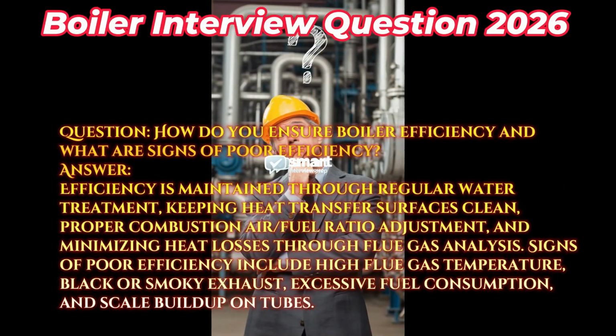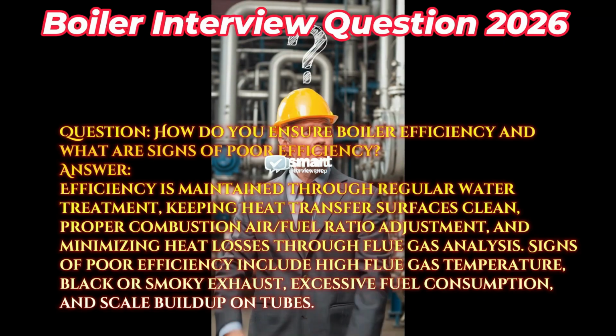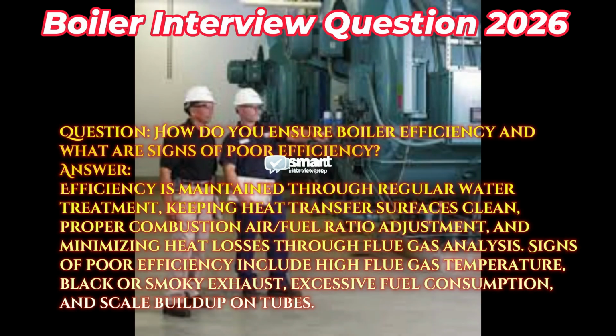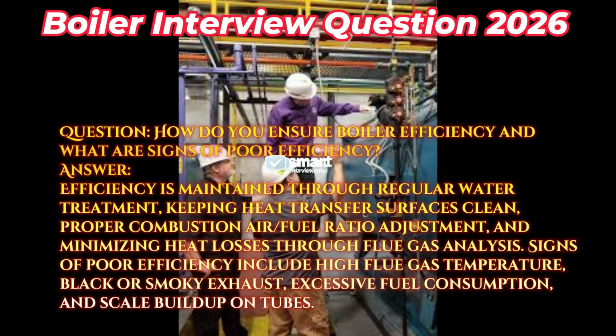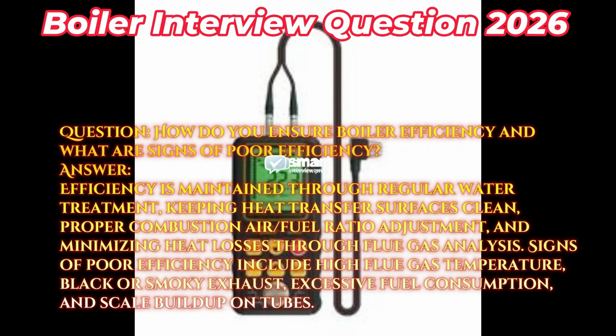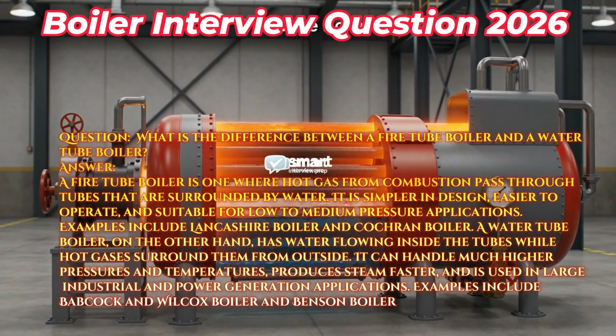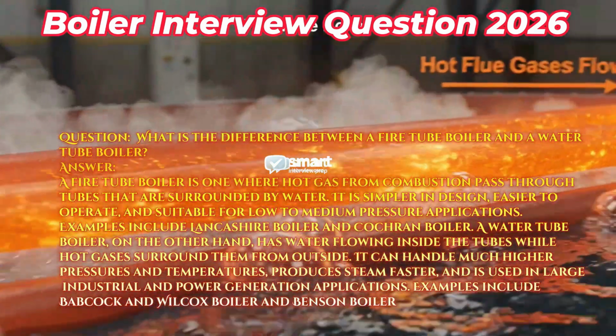Question: how do you ensure boiler efficiency and what are signs of poor efficiency? Answer: efficiency is maintained through regular water treatment, keeping heat transfer surfaces clean, proper combustion air/fuel ratio adjustment, and minimizing heat losses through flue gas analysis. Signs of poor efficiency include high flue gas temperature, black or smoky exhaust, excessive fuel consumption, and scale buildup on tubes.